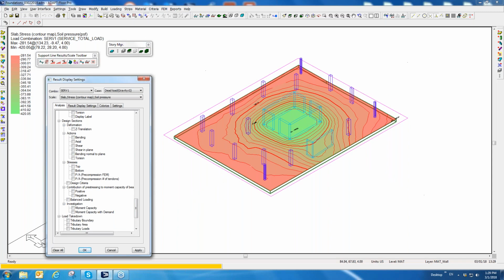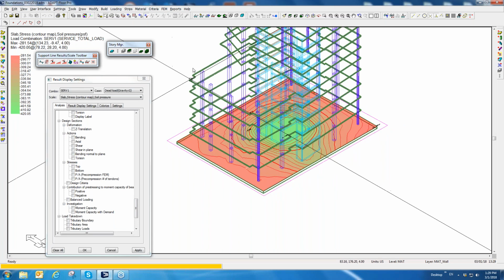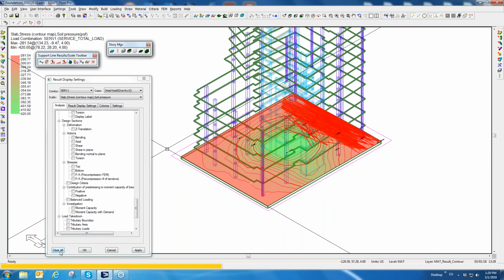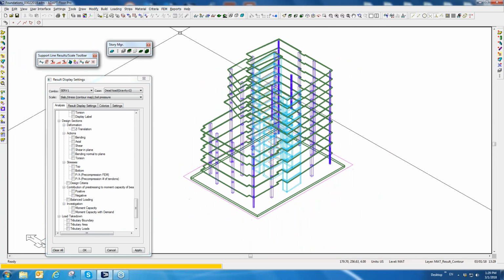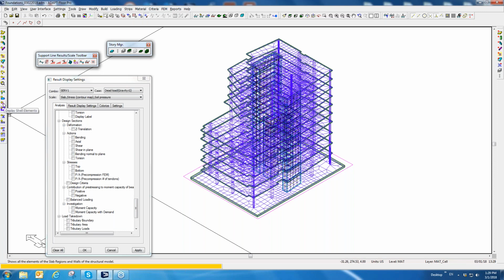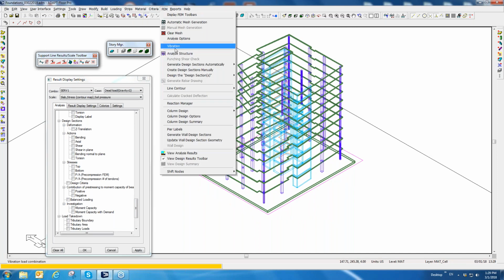Now we're going to take this a step further, and I'm going to go back up to global mode, and let me go ahead and turn off those results. And I'm going to rerun this. I have a mesh in place. I'll turn the mesh on. I've already meshed the model. So this is my FEM. I'm going to now reanalyze the global structure.